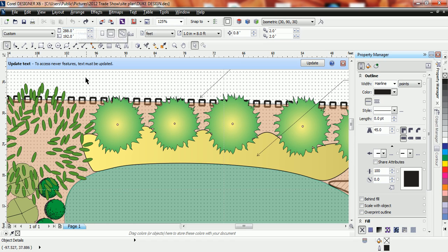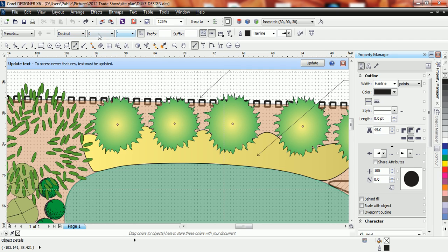I'm going to use my undo button, click on the dimension tool, make your adjustments for how you'd like your dimension tool to read out, left click once on your starting point, drag your cursor over to your next point, and we can even hold our control key or our shift key to make sure that this is a straight edge. Once we get to that second point, release your mouse button, bring your mouse either up or down depending upon where you want this dimension call out labeled, and then you just double click, and that's going to establish or set your dimension tool.